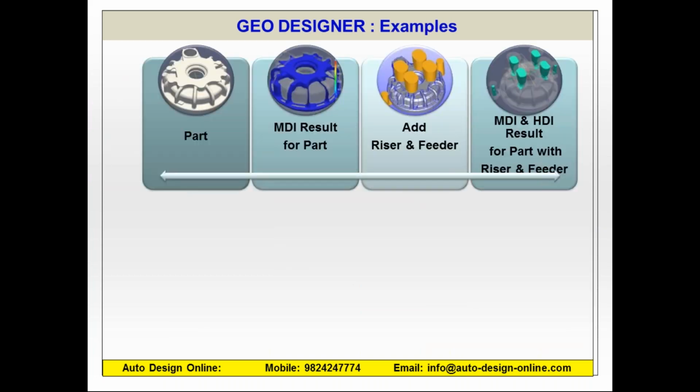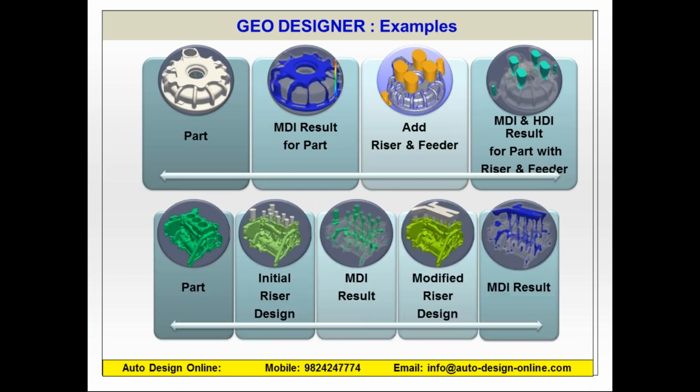Now, another example we can see here is a complex and large part, an engine block. If the risers are provided in this engine block, you can see the riser will dry very quickly. So how can we provide further metal to the riser so we can ensure that it will keep feeding these sections inside the engine block? If you provide such a top side, it will keep feeding material to the engine block, and that's how you can optimize the requirement of your riser, runner, feeder and so forth. This could be useful for different types of casting part irrespective of your process.